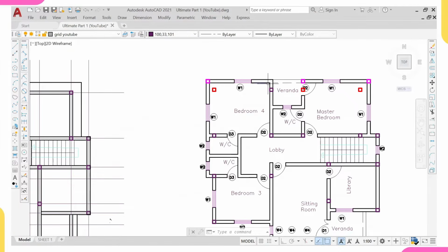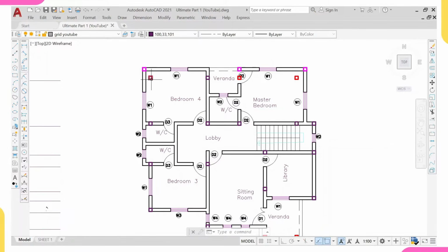Why? These are the new columns that will continue from the first floor. The reason why they will terminate at the ground floor is because they are causing obstruction to this first floor. And these new columns that we have introduced, which are in magenta, are called floating columns. Floating columns are columns that did not start from the foundation. So here you get to learn the governing principle both in floating columns, in paneling, and also in beam arrangement.